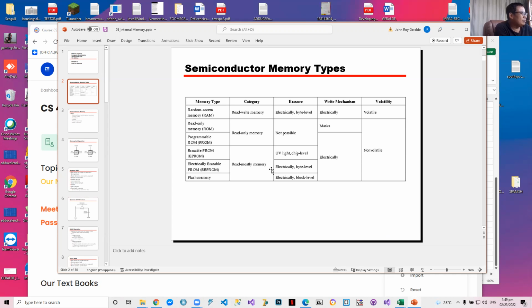Okay, the programmable ROM or PROM is like a ROM that can be programmed, no? Erasable PROM is a PROM that can be erased several times only, not all the times, no? Do you follow? For a limited number of times, you can erase it and write it, erase it and write it. No? Electrically erasable PROM. The meaning of this is you don't need factory equipment to erase the ROM. You can erase it and set it again using your computer.